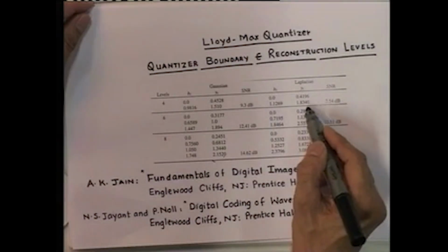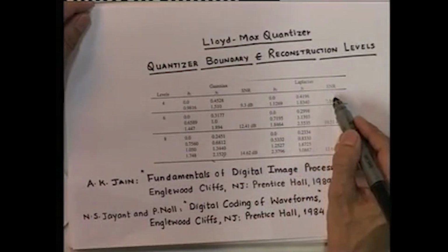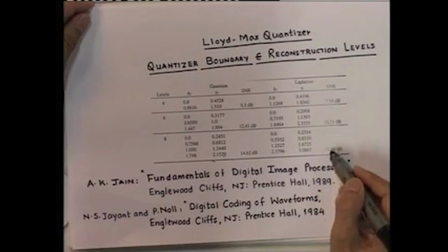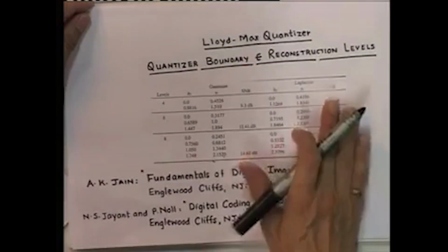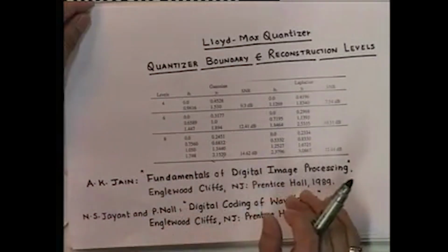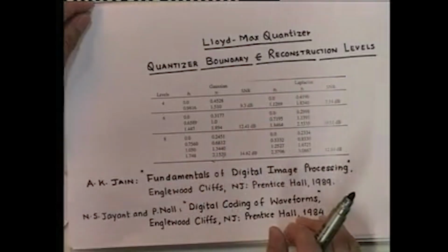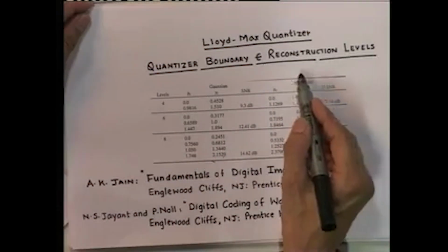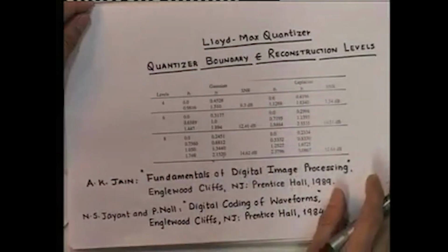However, the same quantizers have smaller inner step sizes because they are more heavily peaked. The SNRs for these quantizers are also listed in this table. Now, if we compare these values with those for the PDF optimized uniform quantizer, we can see a significant improvement, specifically for distributions further away from the uniform distribution.